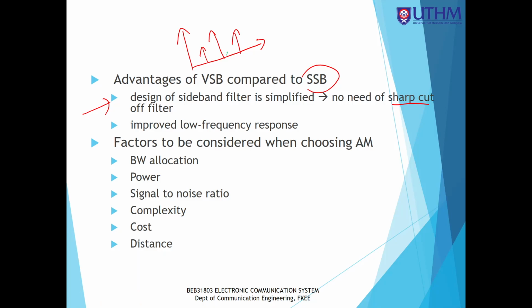The cut-off waveform is more sloped, like this. So if we design a more sharp cut-off filter, it requires a more complex circuit design. The complexity becomes higher, and then this improves the low frequency response.